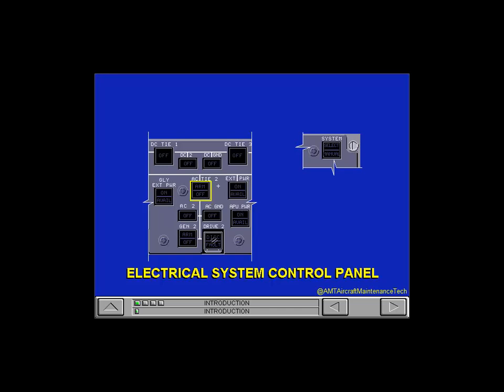If you push an AC tie switch light while the system is in the automatic mode, the manual light will flash. This indication tells you to set the system to the manual mode. The manual light on the system switch flashes. This indication shows the operator that the system can only do the given command in the manual mode. With the system in the automatic mode, the system cannot complete the task. First, set the system switch light to the manual mode, and then set the AC tie switch.